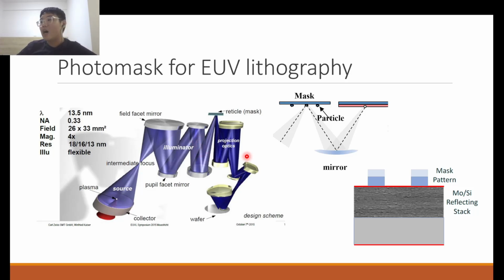So basically, the optics used in the EUV exposure machine is reflection-based optics. The lenses are all mirrors that have a certain curvature to achieve the focusing of the light that gets reflected off them. So as a result, the mask must also be placed on such a mirror.